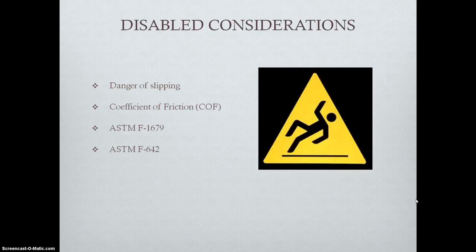There are slip resistance coefficients. 0.50 is the recognized minimum criterion for slip-resistant walking surfaces in courts of the United States. Therefore, if a higher level of slip resistance is desired, the coefficient must be higher than 0.5.